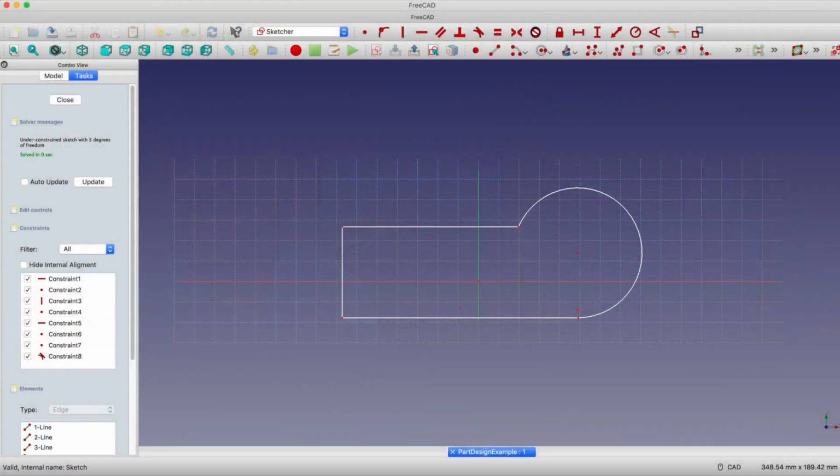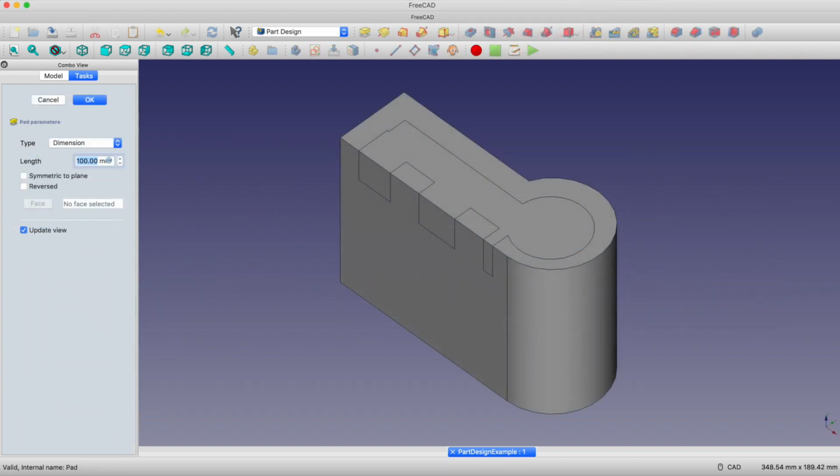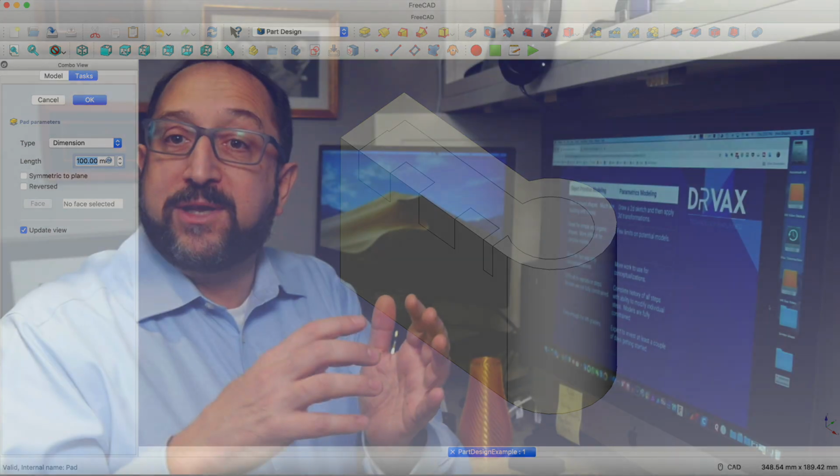In a parametric modeling program, you start with a 2-dimensional drawing, an actual sketch, and then you extrude that sketch into 3-dimensional space. In addition, you can draw sketches that are used to cut material out of your 3-dimensional model. So in parametric modeling, you do a series of steps that often start with a sketch. That series of steps is also completely reproducible.